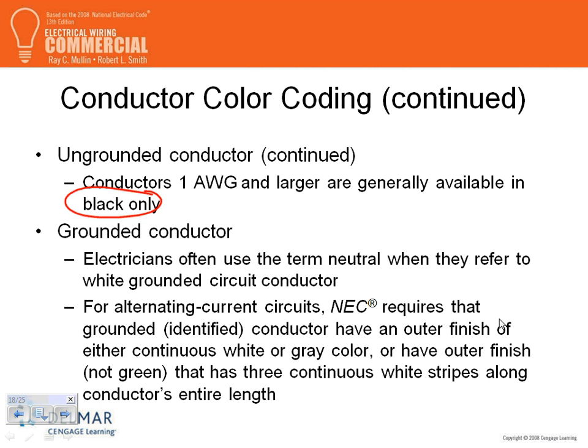But the industry is moving more and more towards color-coded insulation. It's not much of a price difference anymore. If you go to Southwire, guys, they're pushing the color-coded insulation, a little bit more expensive, but not by that much. You can't mix up the phase then. Yes, absolutely. When you're pulling three black conductors, at the beginning you have to be very careful when identifying. It makes the electricians' work much easier if the insulation itself is color coded.